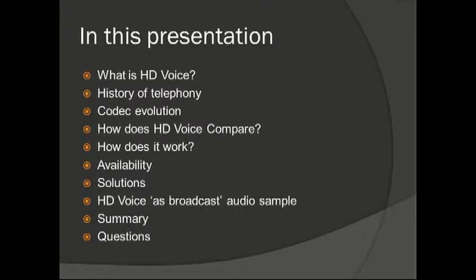So in this presentation we'll look at what is HD Voice. We'll take a brief look at the history of telephony and why we're limited to 3.5 kilohertz. We'll look at the evolution of codecs, how we've got to where we are today and why HD Voice was developed.